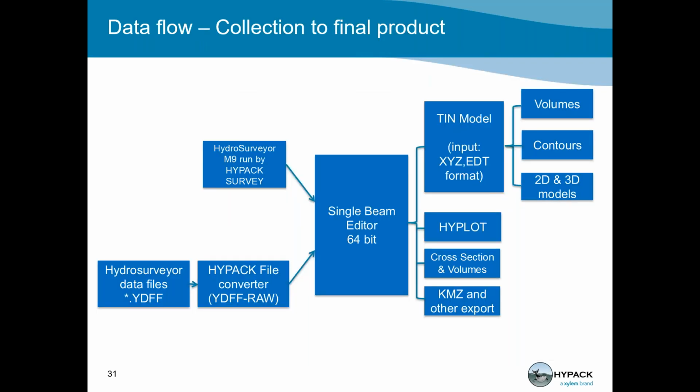That's the general data flow. Once you record your data, either by running HYPACK or just the hydrosurveyor data, which is a different file format called YDFF, they all go into the single beam editor. This is a standard program in HYPACK, and you can edit your data.